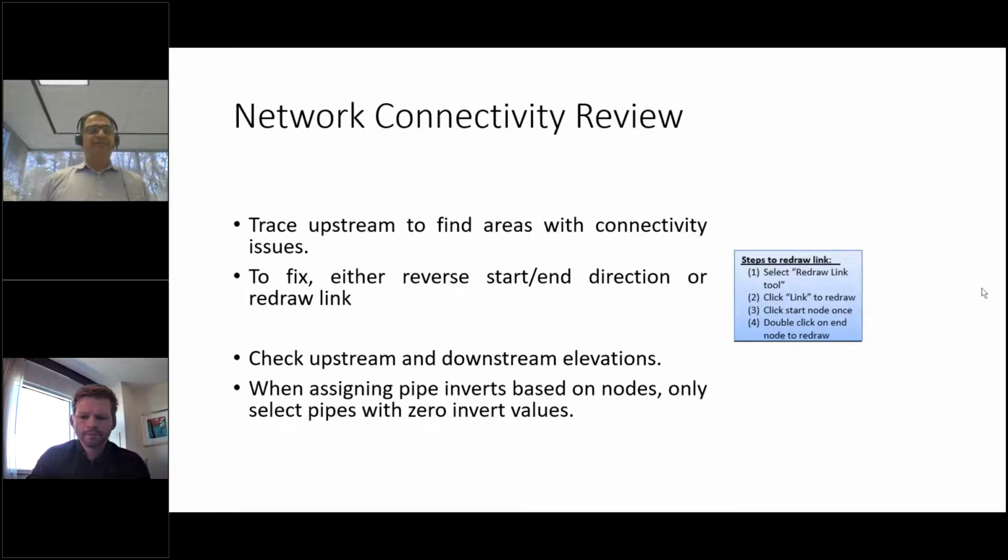I would go ahead and plot the profile of those lines and just make sure it makes sense visually, you know, it makes sense on the screen, because that will get me to a point of, okay, there is an obvious node missing invert, it's set to 0 for some reason, and you'll see the drop on the profile or some negative slope. You'll find those quickly. You'll learn that more and more. I'm a visual person, and a lot of the tools that I like are in that direction.